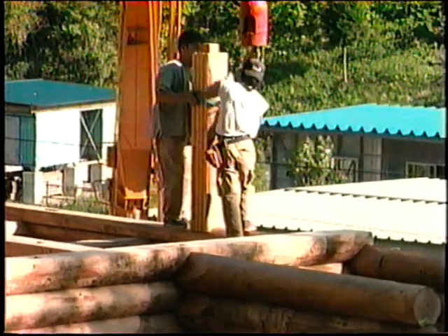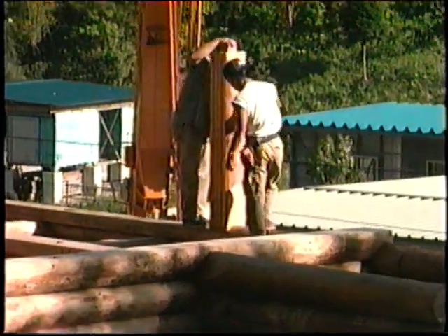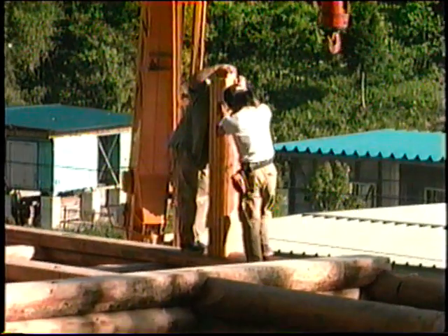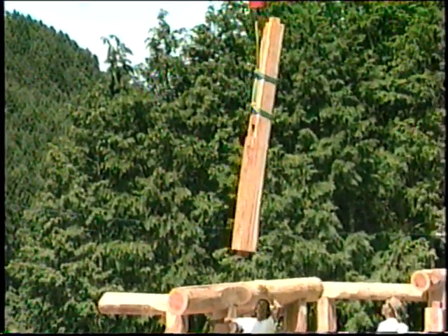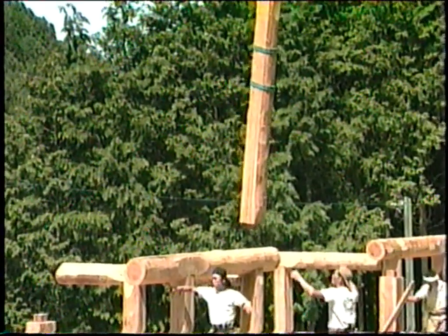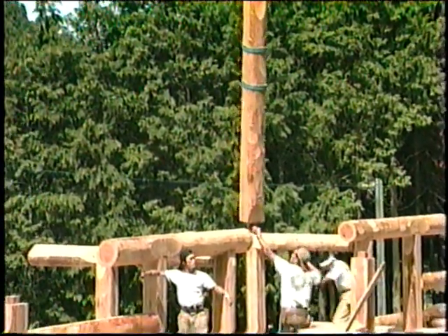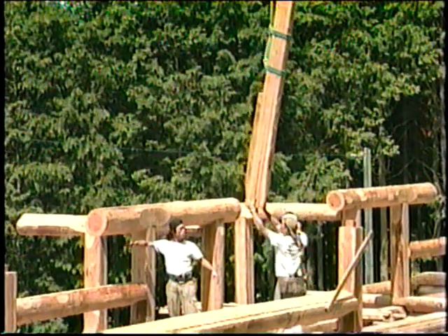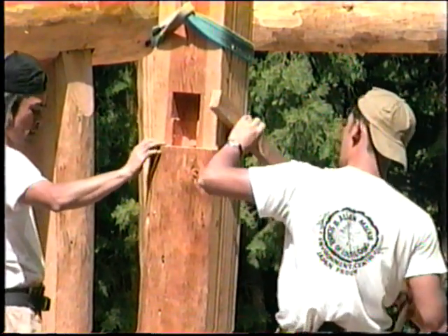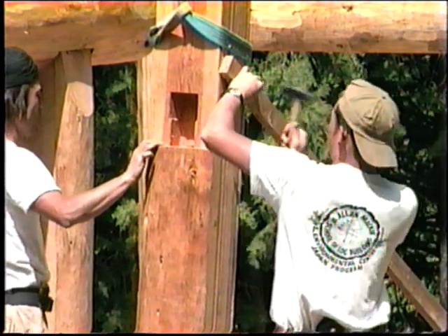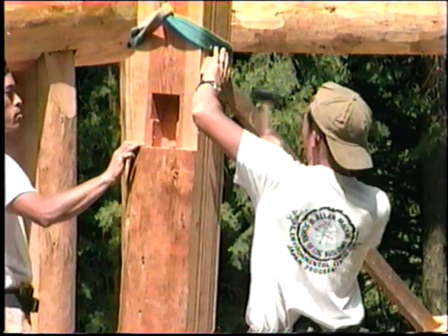This is best accomplished with a crane or hydraulic lift truck. If you do not have access to either of these, there are a number of other devices or procedures that can be used. As each post is positioned, make sure that it is vertical and securely braced so that when the ridge or purlin is placed on it, it will not be in any danger of falling.